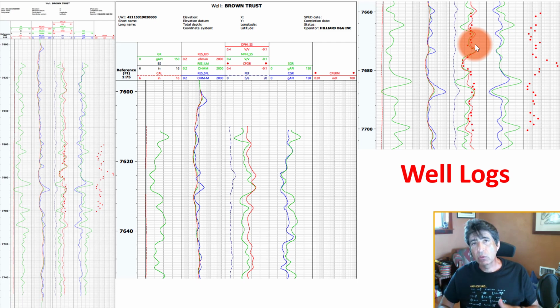And then that core barrel goes through the well and it acquires these cylinders. We saw them in the previous presentation of 3 inches. It can have multiple sizes, but the core barrel replaces the drill bit. And then these cylindrical samples are retrieved and sent all the way to the surface. So we need to have a special procedure to core, and it's expensive. It takes time. It slows down the drilling process, so we need to know exactly when one has to core.